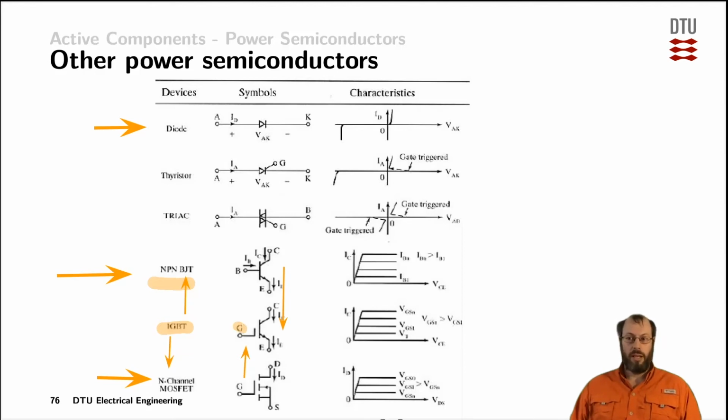It has a gate, it has a collector, and it has an emitter, where the gate is inherited from the MOSFET's gate drive behavior, and the collector and the emitter are inherited from the BJT. In modern practical applications, IGBTs show up at voltages where MOSFETs cannot withstand the blocking anymore. And practically that range starts at about 1200 volts, and the next category of IGBTs are 1500 volts.